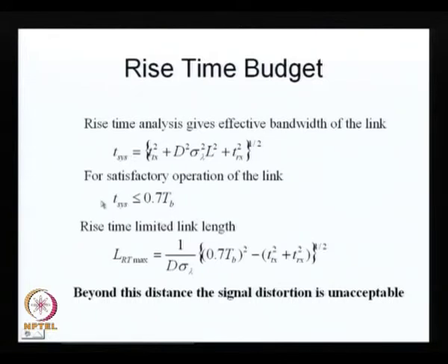Now, the standard is that for a satisfactory reception of the bits, the system rise time should be less than 70% of the bit duration.